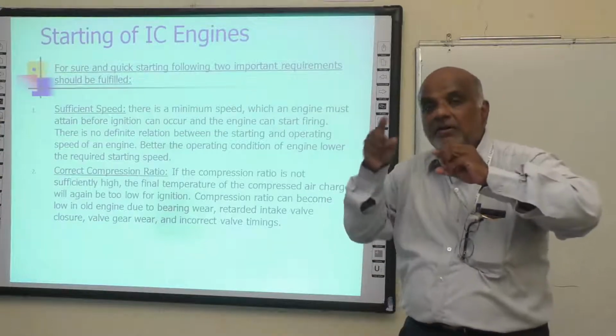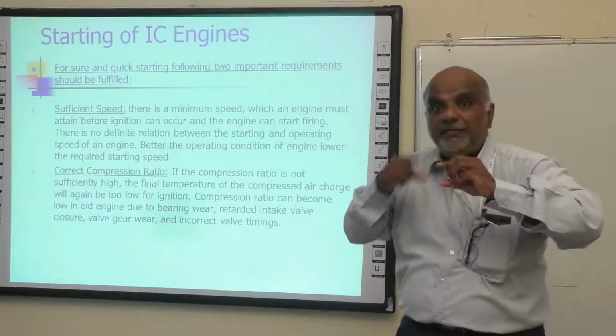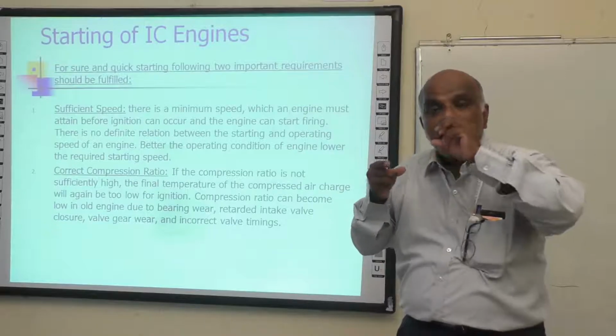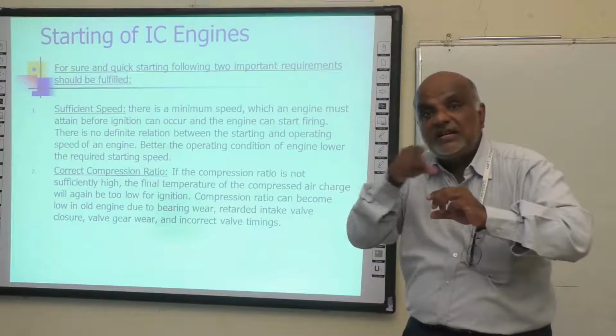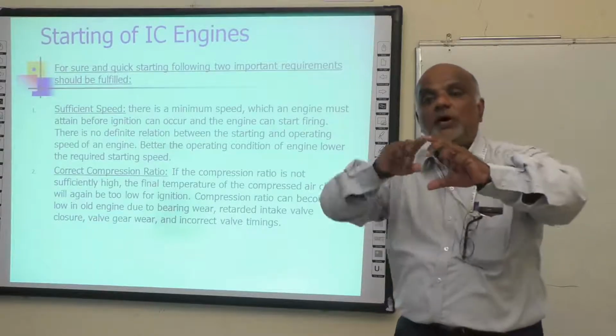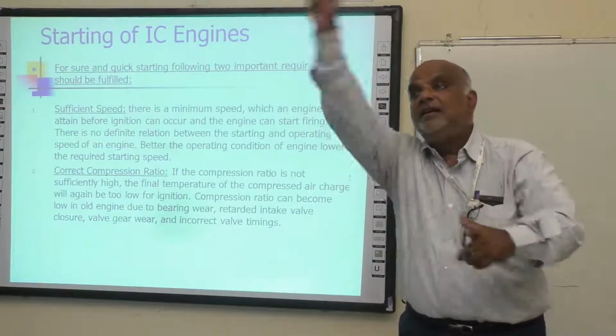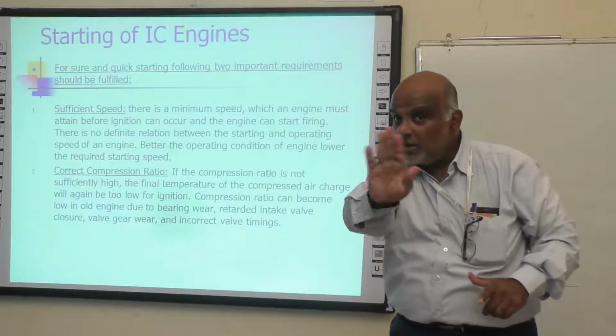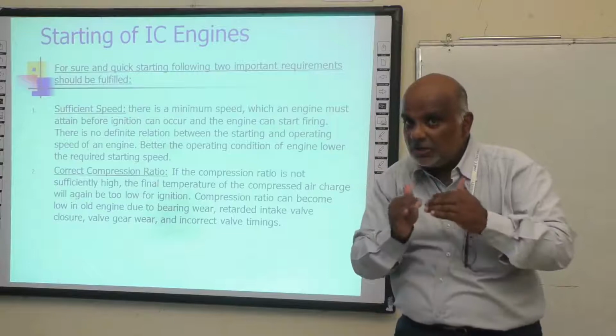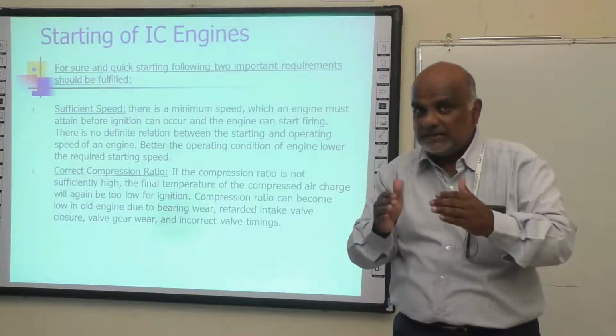As it rotates at a very high RPM of 1000 RPM, this Bendix gear, due to the centrifugal force, moves forward and gets into the flywheel grip. In the bike, I'm still not coming to the ship's one, I'm still talking about the motorcycle.